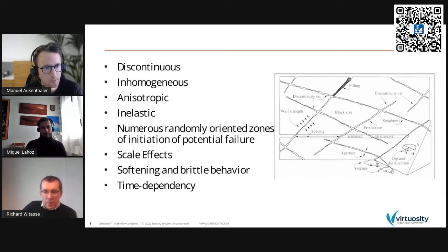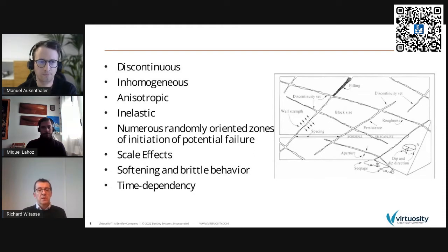Yeah. Well, indeed, Manuel, you are providing an exhaustive list of relevant aspects that might be considered during a finite element analysis or during an analytical analysis in general, not specifically finite element. Some of those characteristics are relevant to geomaterials, and some of them are even more specific to rock masses. With that respect, I would say the first one, the fact that you may be dealing in some situations with a discontinuous media, is very particular to rock. Indeed, we do have within this material sets of joints, fracture joints, which could be in any direction, and along which lower strength properties are expected. This is something that needs to be addressed properly.